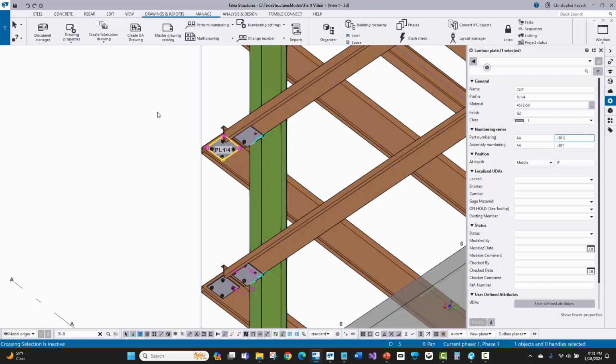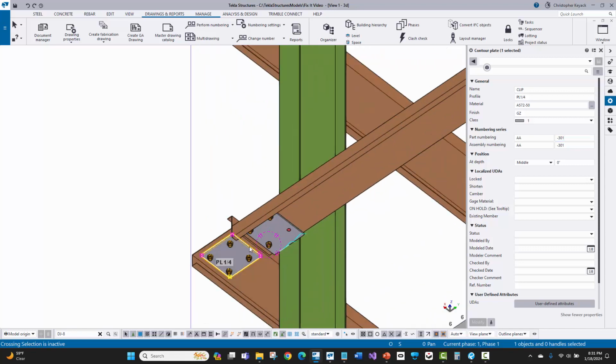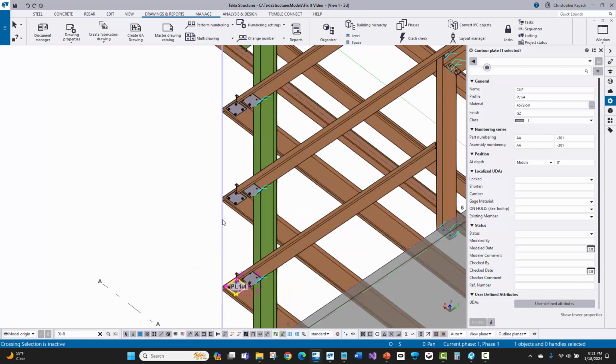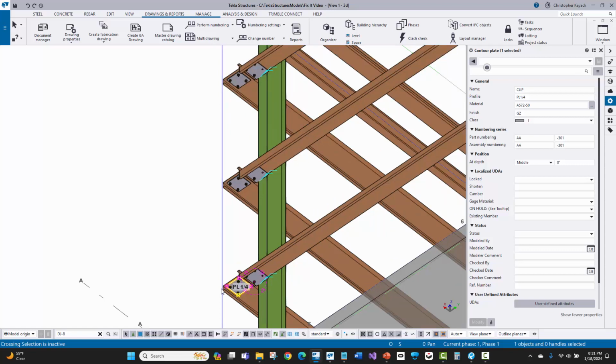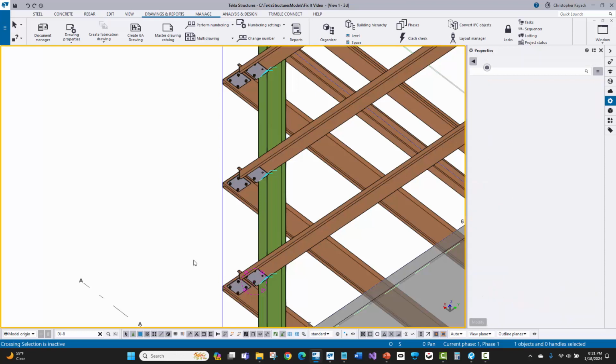Now, why when I opened the drawing did I still see the holes offset? Well, it's probably because the one that I fixed was not the instance of the individual part in the model that the drawing was made from. So whenever you have a multiple quantity, like here I have a quantity of 3, one of the pieces in the model is actually picked to make the drawing from. And I just happened to have the one that was picked where the drawing was made from was not the one that I had first fixed. So that's just a good education lesson on what was going on there. It kind of confused me and made me question what was happening. And it was because I had the mark forced.